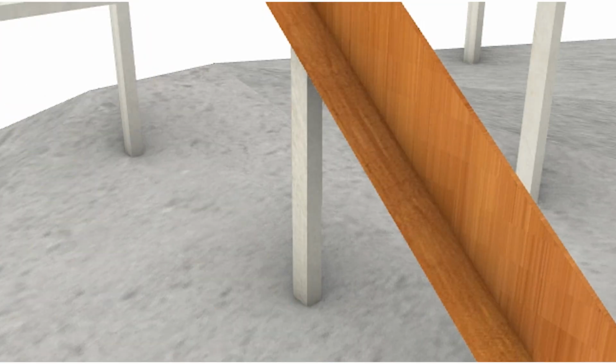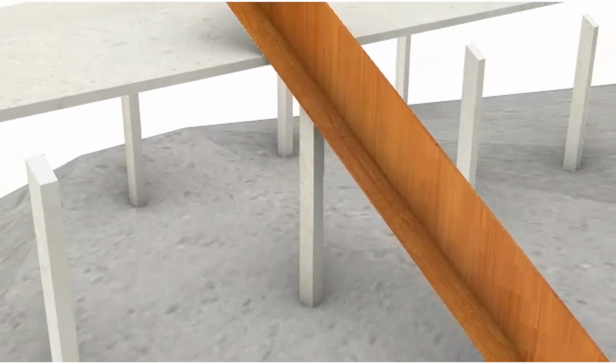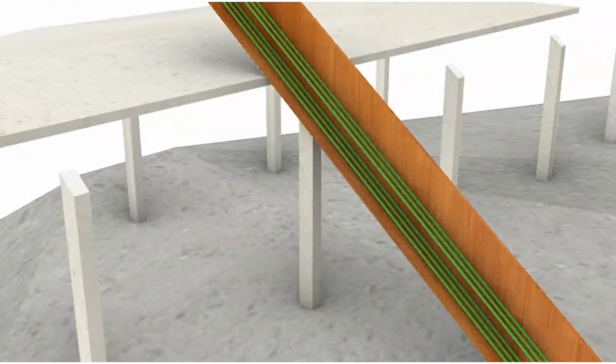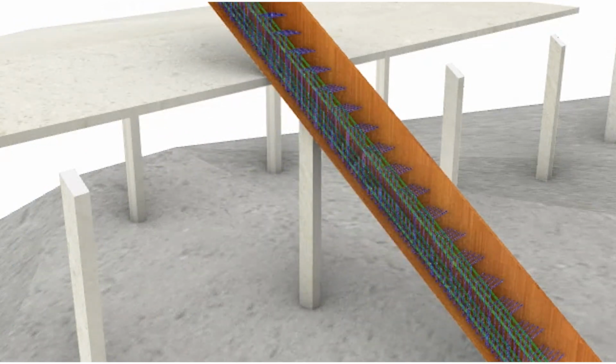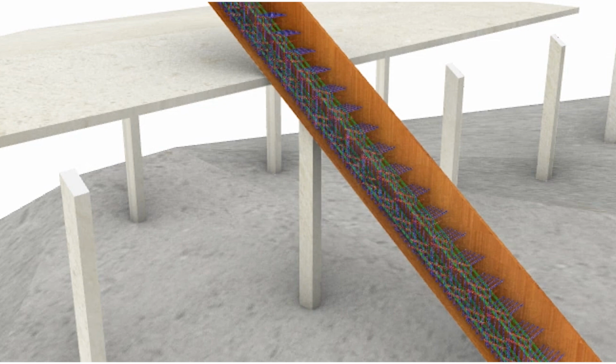Diagonal rebar is first installed along the bottom of the beam to resist torsion and diagonal shear cracking, particularly important when bending and shear stresses interact. Next, longitudinal rebar is placed along the beam's length to counter both positive and negative bending moments of up to 1,100 kN, compensating for concrete's low tensile strength. Finally, horizontal stirrups are installed to encircle the beam cross-section and resist up to 450 kN of pure shear load.